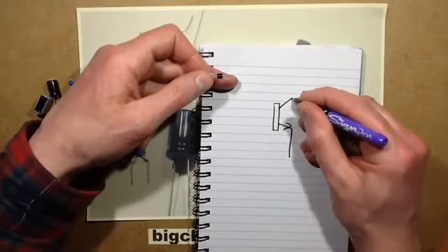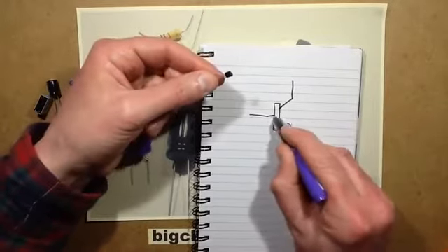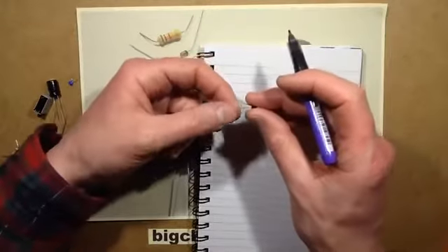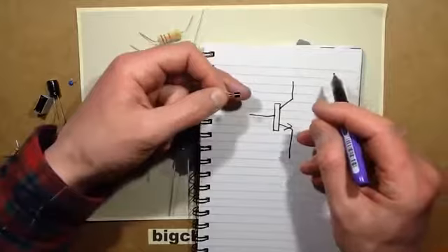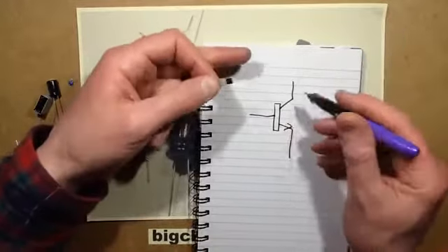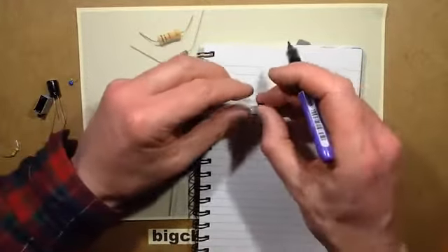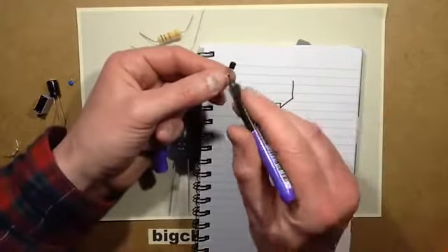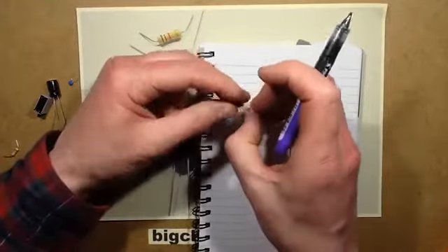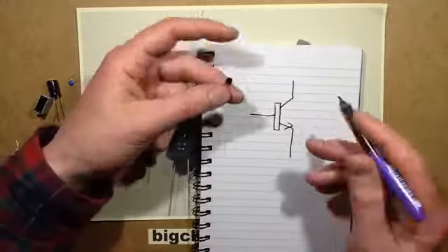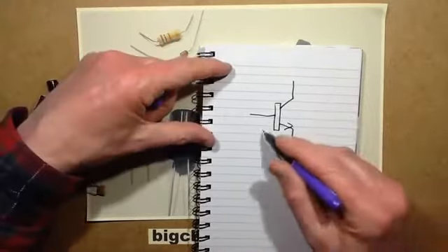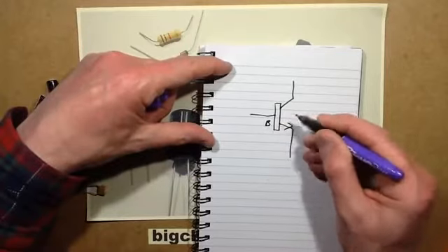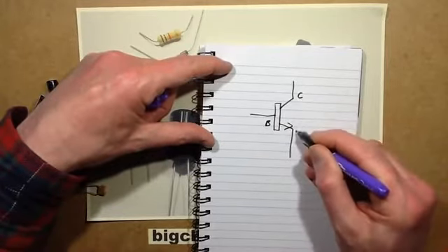You get 3 pins, and if you ever want to find out what the pinout for your transistor is, if you're not 100% sure, just go on Google and type its number in, like 2N3904. Google it, look for images, and you'll find pictures of the transistor with the actual pin designations printed under them. It just makes it very easy to find data like that. So it's got 3 pins: the base pin, the collector pin, and the emitter pin.